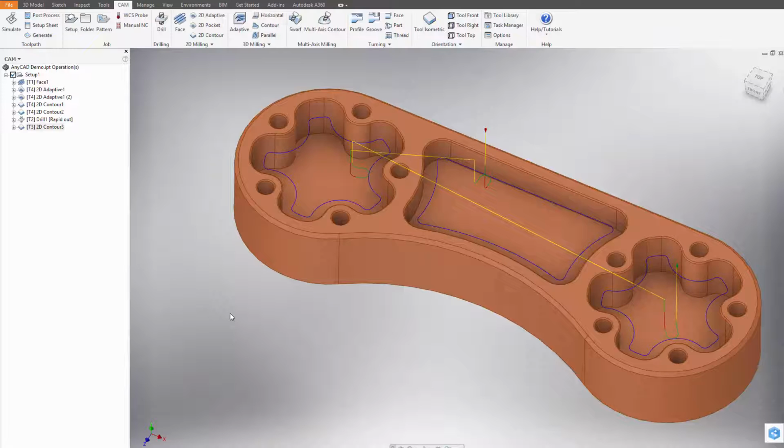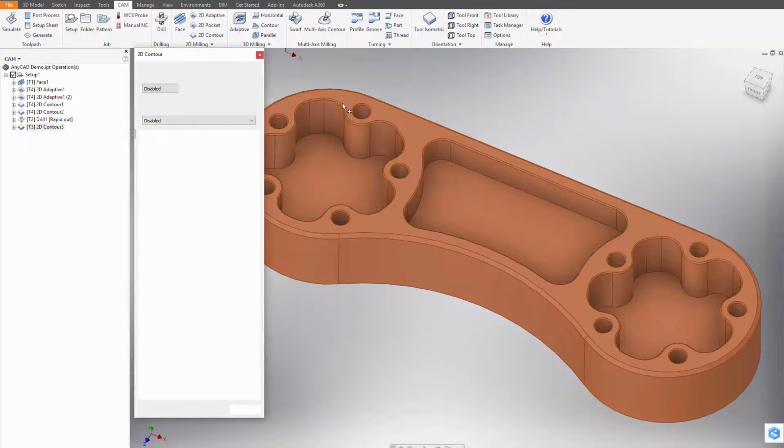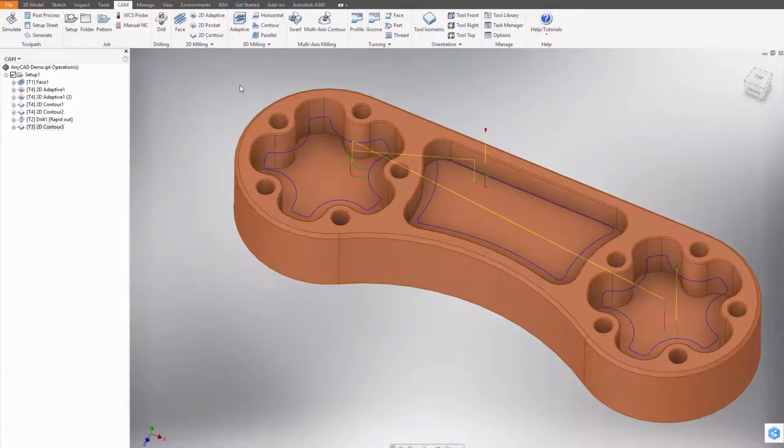It works 99% of the time. Obviously if I had a quantity 5 pattern and I selected a hole as the base hole to go and find the rest of the holes, and then that particular hole disappeared, the toolpath would fail to calculate, and I'd have to come in here and reselect that piece of geometry, which is, you know, perfectly reasonable to expect. But all of the other stuff I didn't have to toolpath, I didn't have to reselect anything, and I'm good to go. And so yeah, you saw me do that with Solidworks.